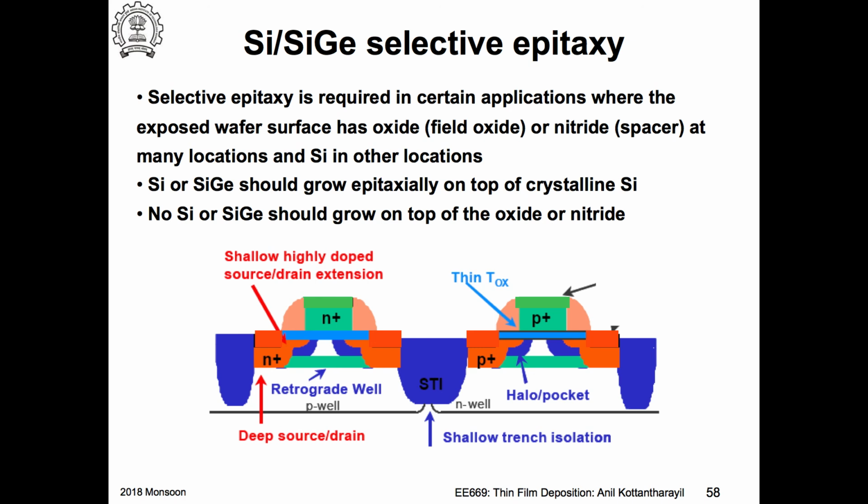So you are depositing the mono and poly at the same rate, right? And then you are etching, but because the polycrystalline silicon is defective, it will be etched faster. Monocrystalline would also be etched, but much slower. So we need to now add an etchant. So that is what it is.